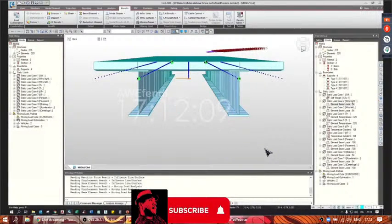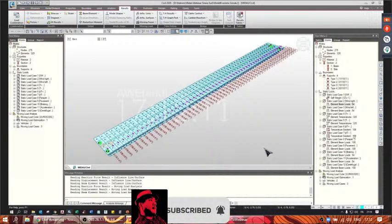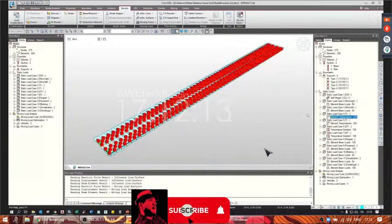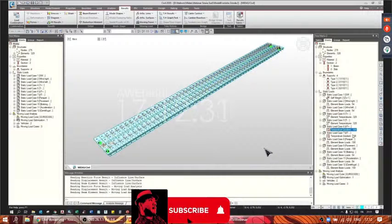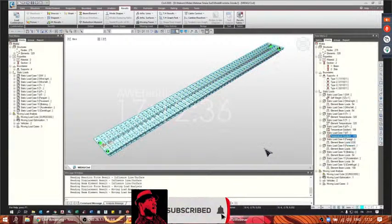The uniform temperature load, now I can show you. Okay. That is calculated with the uniform temperature applied on every element present in the model, and is calculated with maps that we can find in the Romanian code. The gradient temperature is applied directly on beams. We have a positive one and a negative one, depending on which one is the warmer side of the beam.